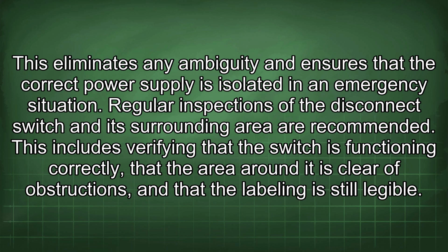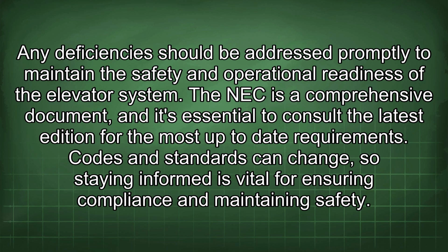Regular inspections of the disconnect switch and its surrounding area are recommended. This includes verifying that the switch is functioning correctly, that the area around it is clear of obstructions, and that the labeling is still legible. Any deficiencies should be addressed promptly to maintain the safety and operational readiness of the elevator system.